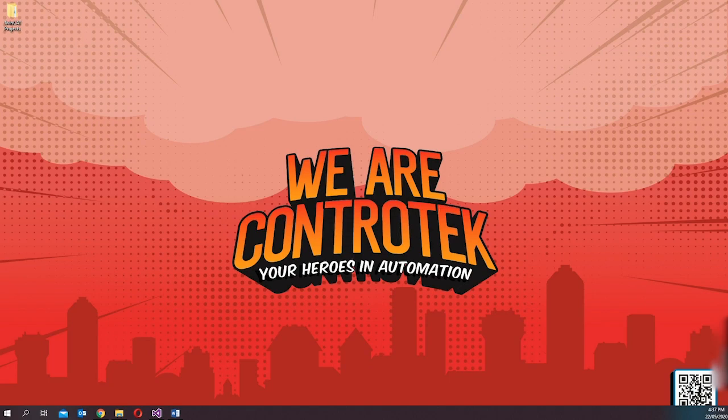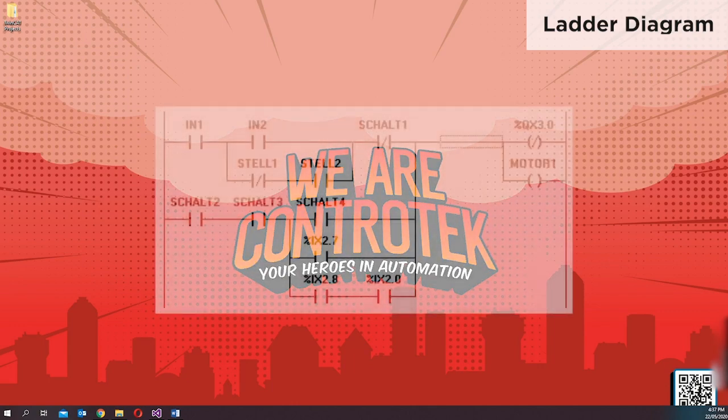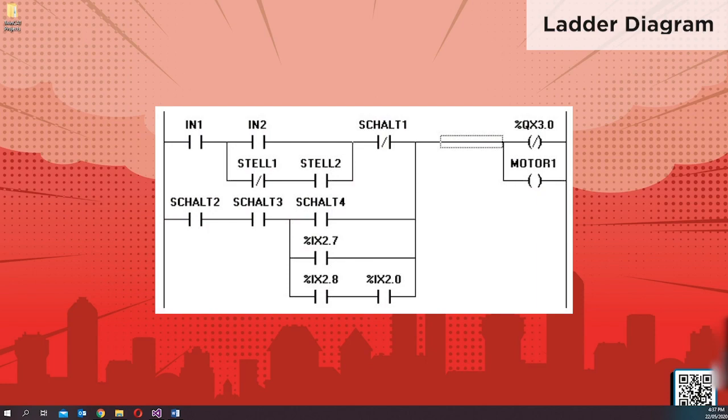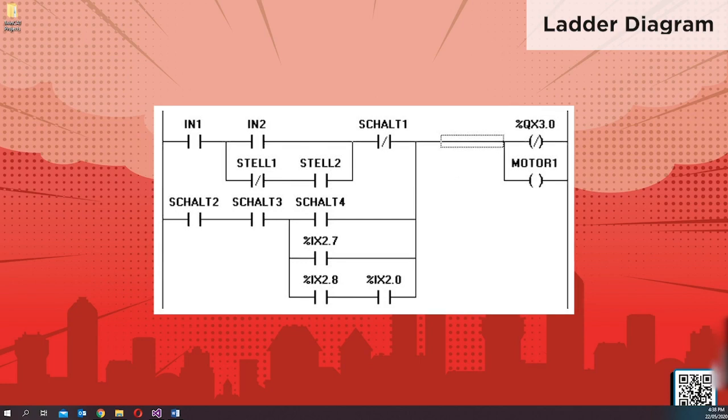I will begin with the most commonly used PLC programming language in the automation industry, which is ladder diagram. The ladder diagram is also a graphics-oriented programming language which approaches the structure of an electric circuit. The history behind this is it replaced the conventional relay racks or relay logics and was developed into a PLC programming language that is really similar to the graphical representation of electrical schematics of relays. The ladder diagram is suitable for constructing logical switches.